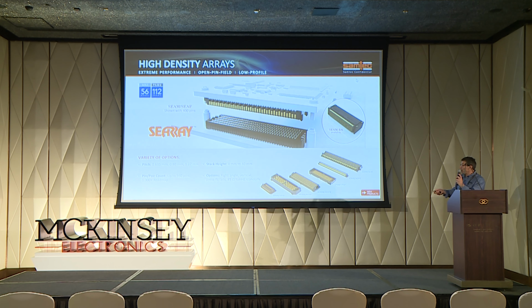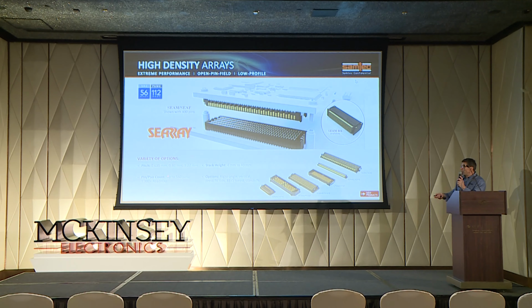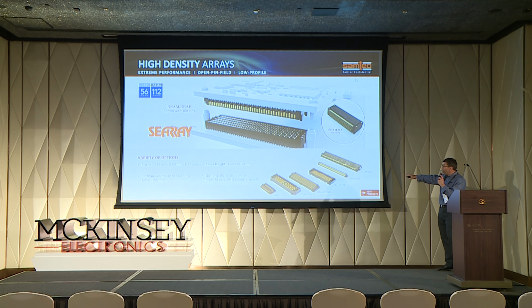And we get different stack heights, 4 mil to 40 mil. It's on a 1.27 mil pitch. Other pitches available, different series, and we can get up to 560 pins. But we show here on the bottom side of the screen, we've got Accelerate performance, Nova array, C array, different array types based on whether you want density, low stack height, or best performance. So a whole range of products available in the array series, depending on what you want to do.